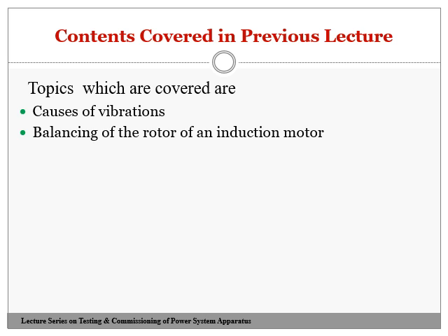Those may be due to a bearing problem, or a shaft problem, or an unbalanced rotor, or loose foundation bolts. Those are the causes of the vibrations.